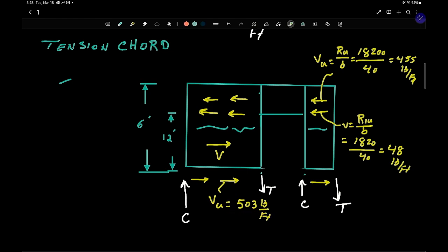And as the movement happens from left to right, the other way, the shear comes this way. So basically, a force coming like this at this angle puts this right here in compression, and this goes in tension, and again this goes in compression, this goes in tension. So let's calculate these.